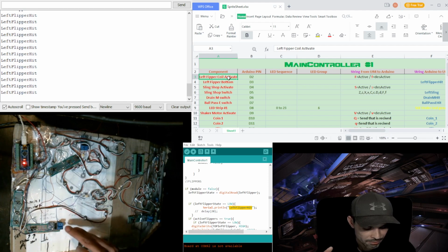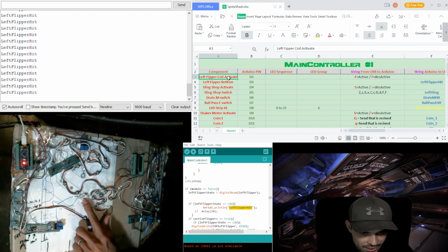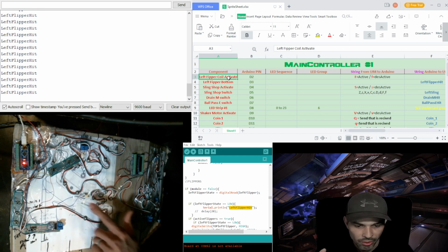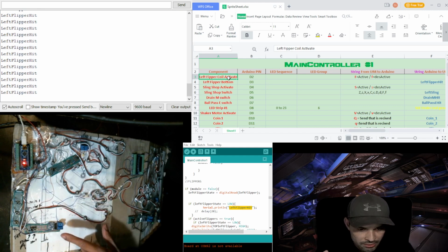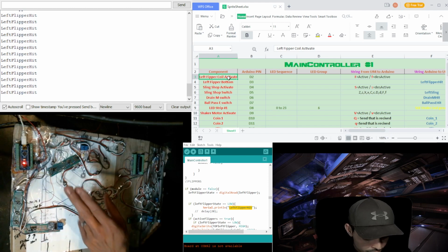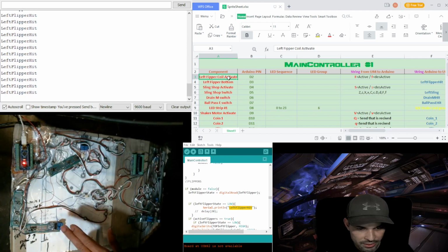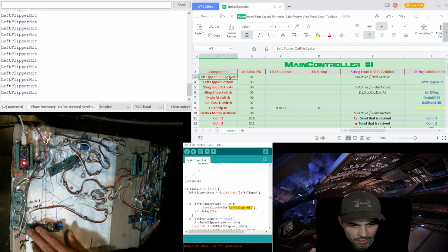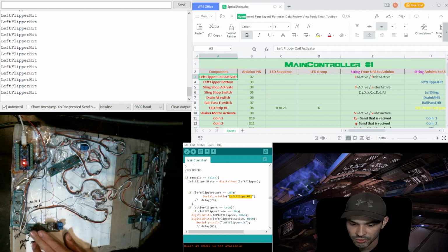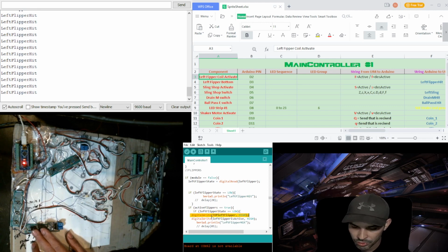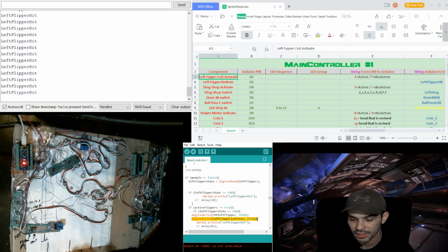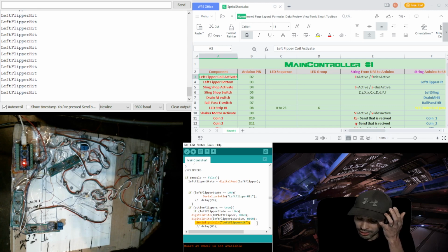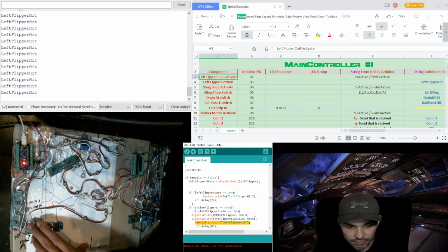And now the input, I'm using 5 volts for everything, because I got a light here that represents my flipper coil, okay? So when this light comes on, that means that this is being triggered by the Arduino to tell this to come on and bypass the 48 volts in the case of pinball. But right now nothing happened, because I got a function here that says if this is true and is low, it will do the top flipper, and also it will activate the flipper, and as well it will trigger another print. So let's see that.